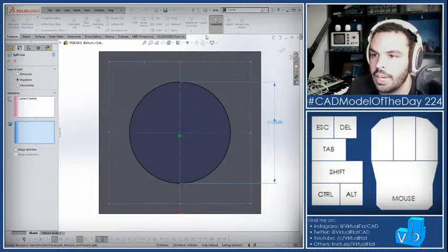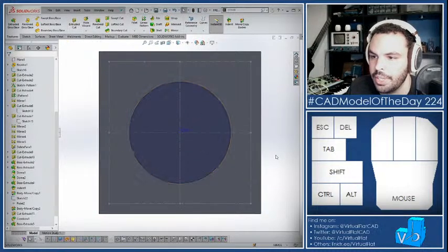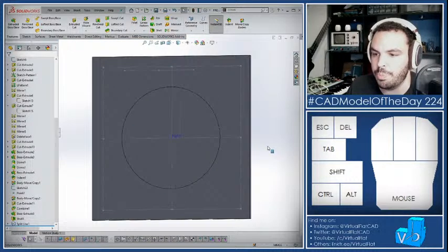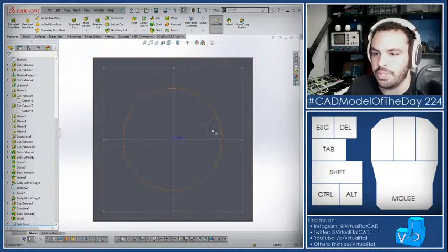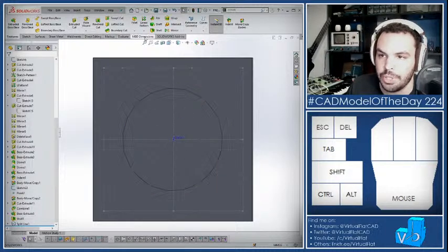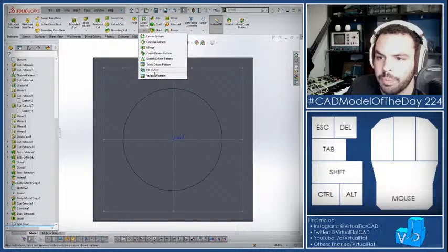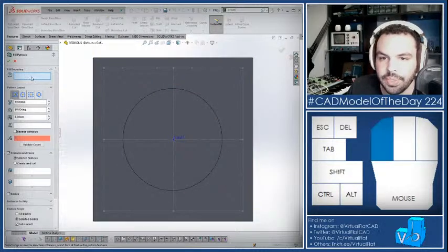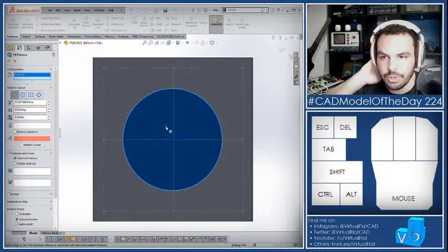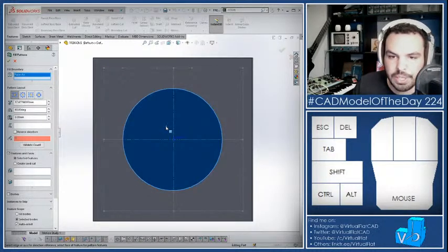And I will split the face like this. So split line means just cut the face into 2 pieces. It doesn't actually punch anything through, but I will use this as my boundary. So you'll see what I mean. Fill pattern. So fill boundary will be our new split face like that.